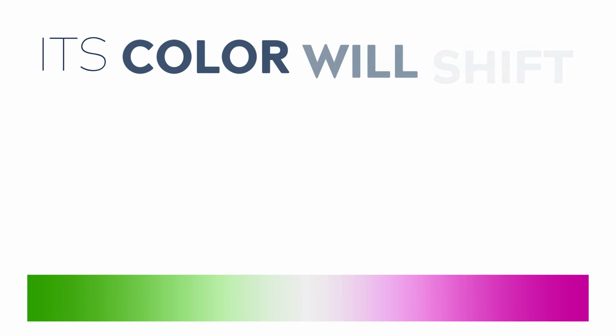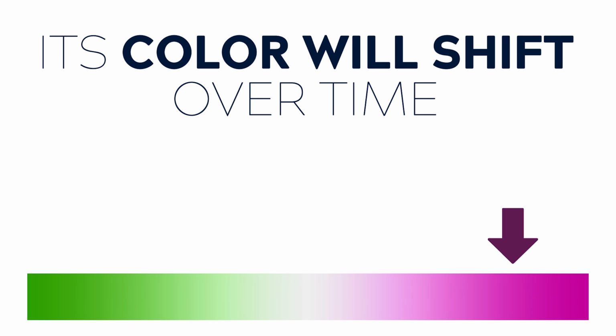The color temperature and CRI of HMIs is determined by the specific mix of chemicals within each globe. So this is why producing them can be quite complex. The mercury within the bulb will also start to burn off slowly over time. This means that as they age, the bulb's color temperature will actually shift towards different colors, meaning that you'll have to eventually correct this with correction gels.